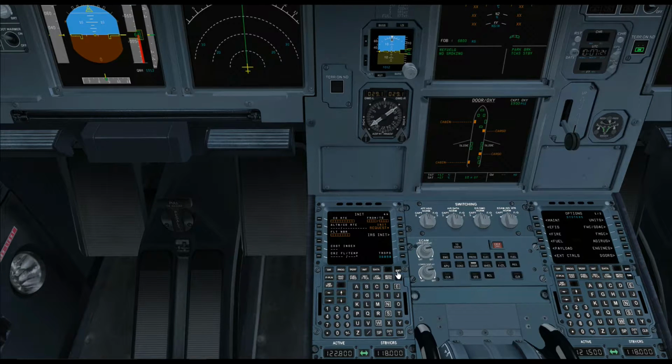However, the FS Labs A320X has a really nice feature which simulates the AOC. So what we can do, as long as we've pre-filed our flight plan either on VATSIM or on IVAO, I'm on VATSIM, and I've pre-filed our flight plan. So selecting the flight number here as filed with VATSIM, and then selecting the init request feature, and hopefully our flight plan information will pop up automatically. Yep, there it is. So we have the flight plan uplink legend here,